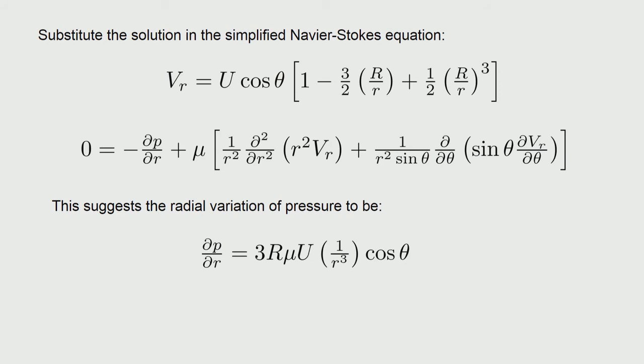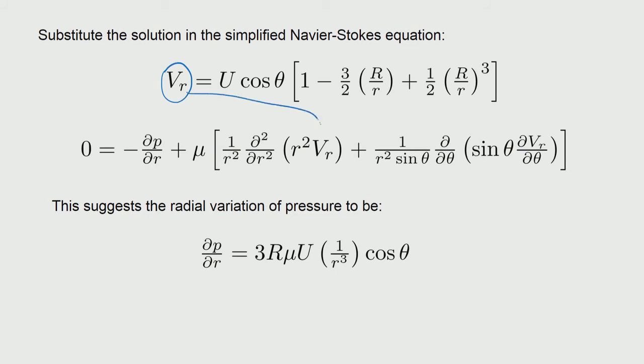Okay. So, for that, what we need to do is go one step back and look at the Navier-Stokes equation, substitute the velocities and get the pressure distributions. If you have noticed in the previous session, we have already done that to see how the pressure variation will come once we have the velocity components available. So, we are going to do that here also. So, the velocity components are available. So, then we substitute that into the Navier-Stokes equation, but keeping the pressure variations intact, so that we can get some functional form for P.